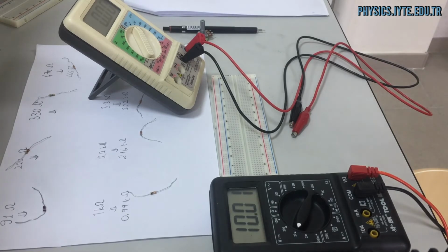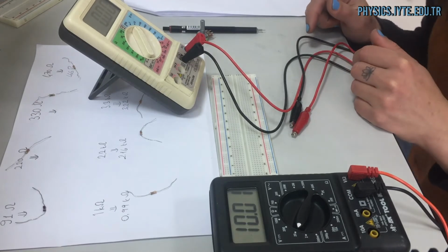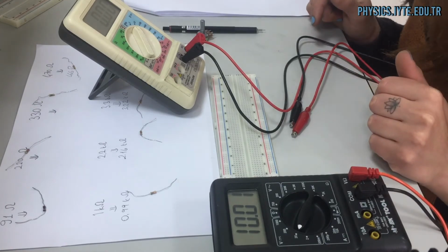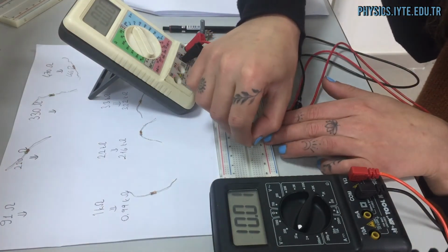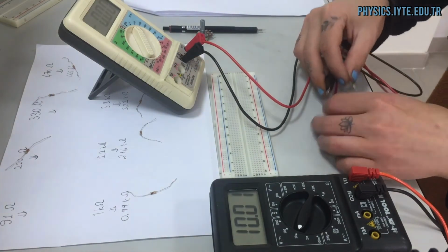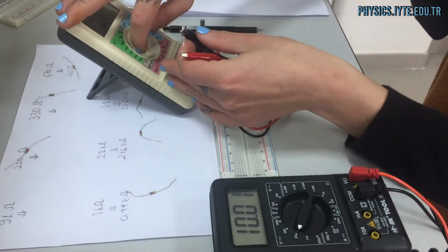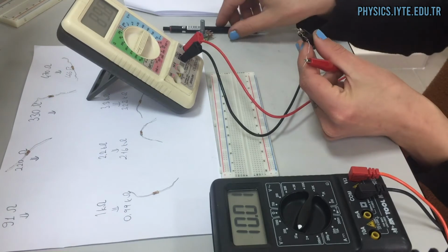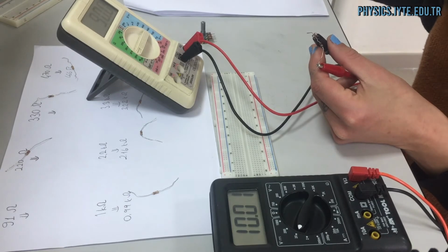In the last part of the experiment, maximum power transfer will be realized with experimental approach. To do that, a voltage source of 10 DC volts will be used and a 91 ohm resistance will be used. Before that, we measure the actual values of those resistors. And we will note the resistance 1 as 90 ohms.